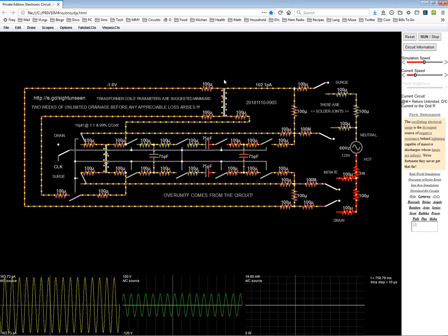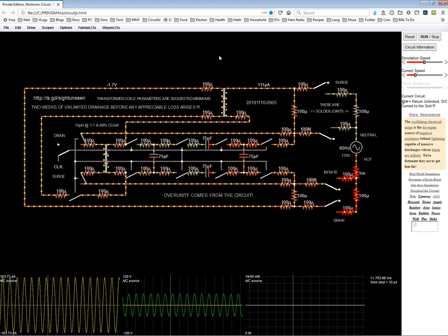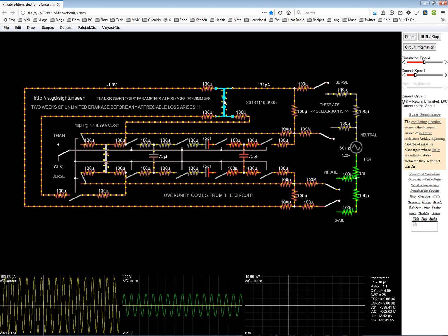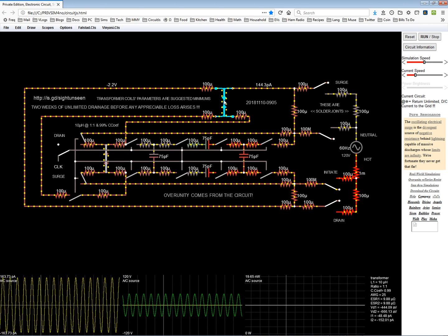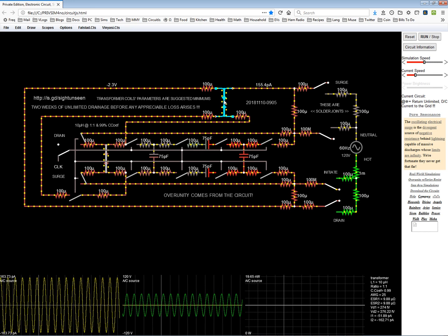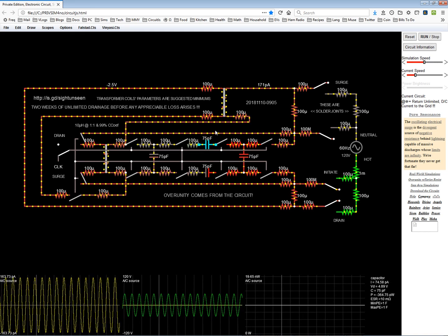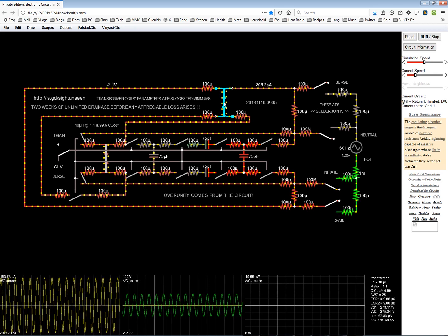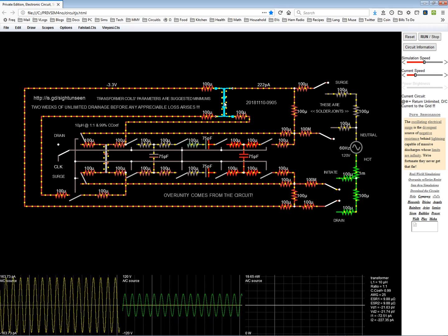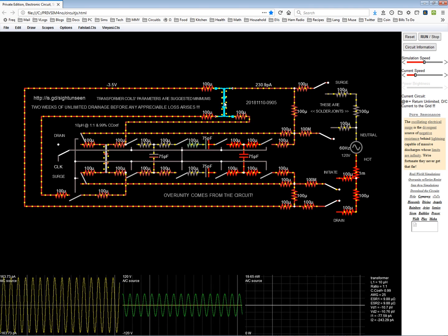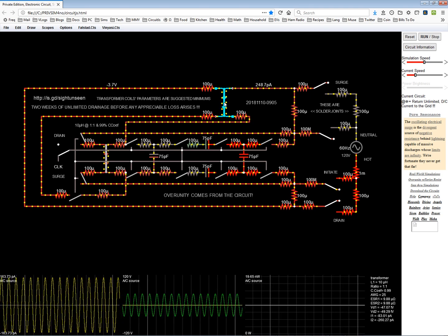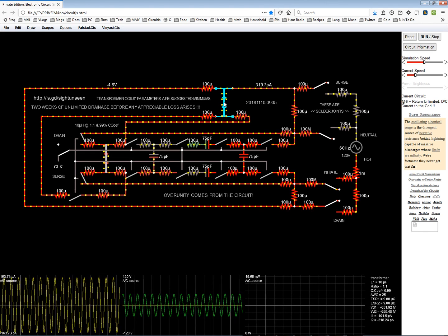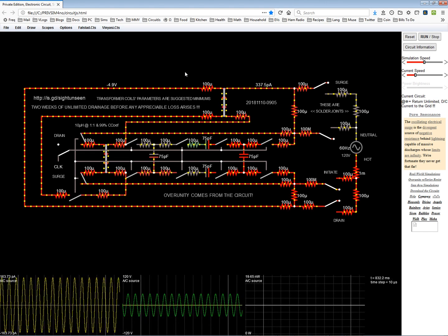Now the size of the coils on the transformers are just suggested minimums. I found that 99% coupling coefficient was the minimum. That's the requirement. And anything else is really up to you, how big you make your coils, how big your capacitors are. But 99% coupling coefficient seems to be a minimum, because when I had it at 90% coupling coefficient, it didn't work. But 99% worked. So you don't need 3 nines, and 1 nine is not enough, but 2 nines is pretty good. In fact, 2 nines works.